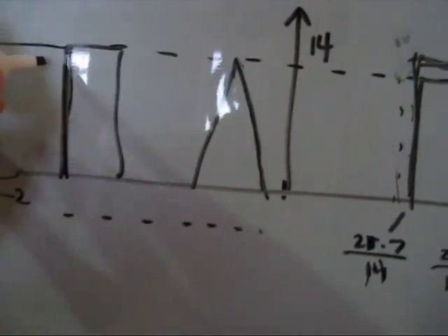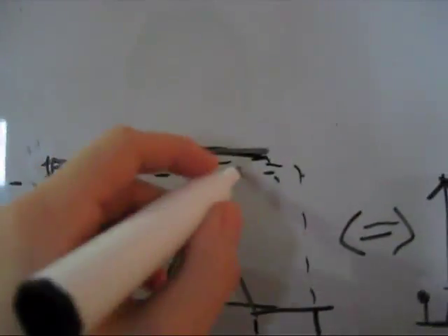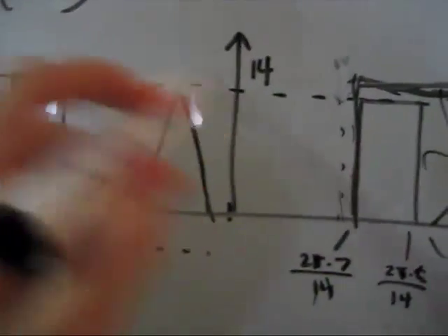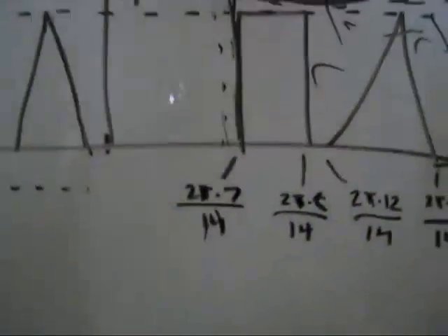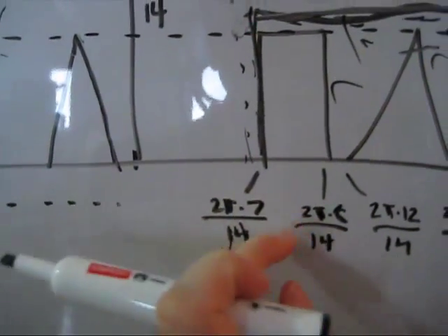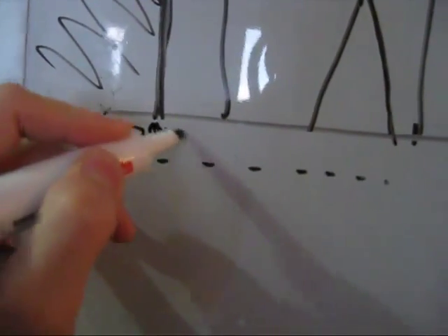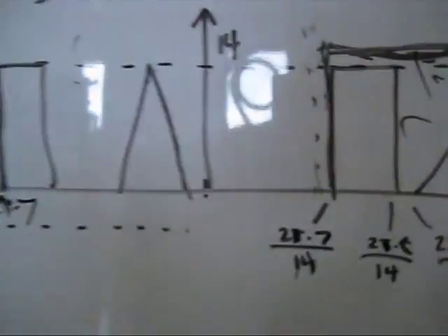So this is our filter, and this is our filter over here. Those are the parts that we're keeping, and we're filtering out these parts here. I'm filtering out up to plus 7 hertz and up to minus 7 hertz, or 2 pi 7 radians per second.